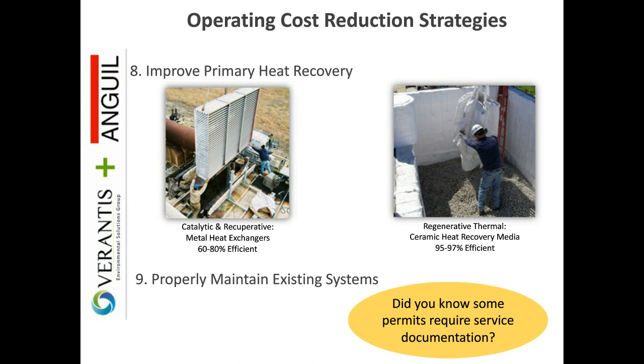Bullet item number 9 here. This is one of the things that people tend to not think about either. We've seen it quite often actually where air permits, the permit itself, has required the end user to perform annual maintenance. So not only does it help in terms of maintaining the useful life of the system and operating costs, in many cases it can also be a requirement in the permit itself.